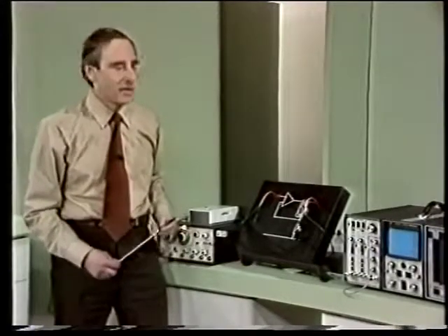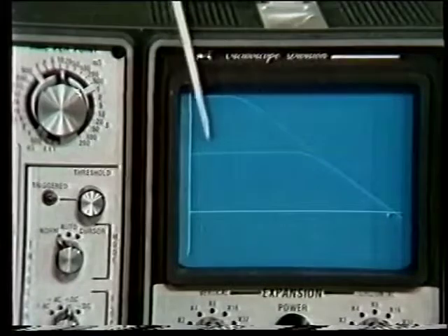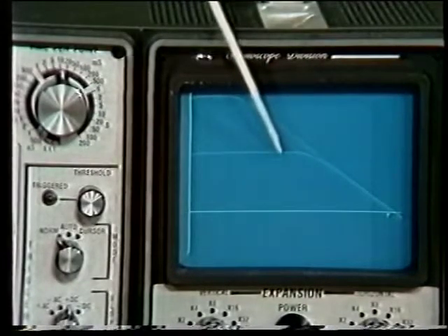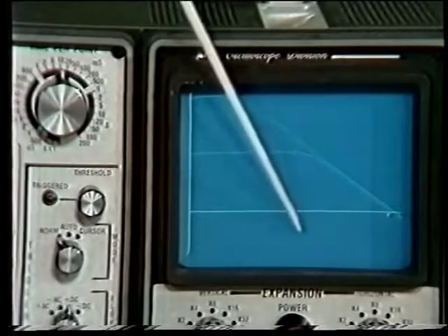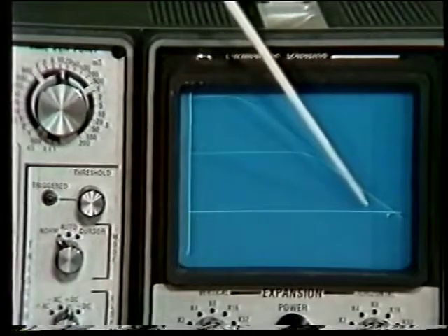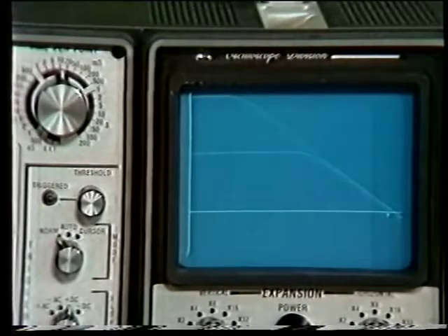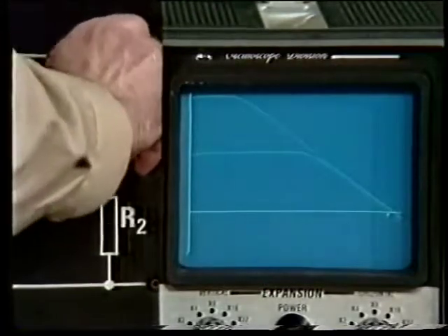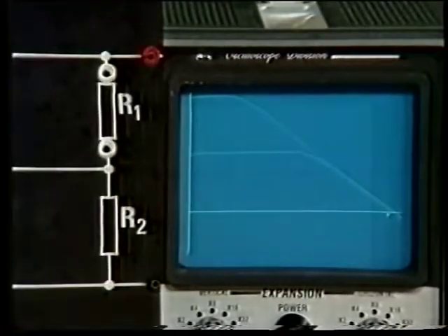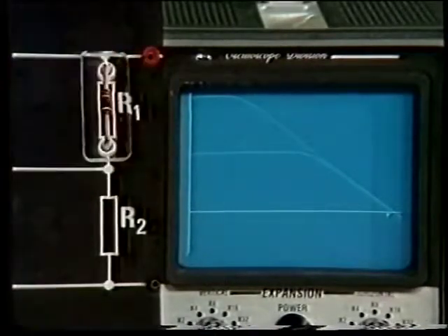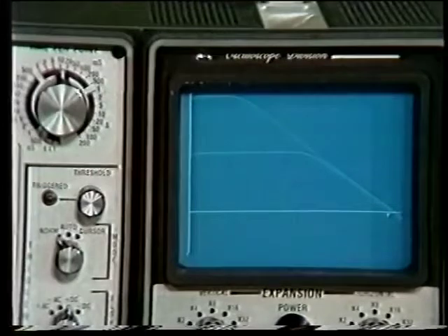Now for the second curve with R1 equal to 99 kilo ohm. The gain for the horizontal bit is 40 dB, that's 100. The 3 dB frequency is at about 10 kilohertz. Then the two curves join together. I'll just plug in a second value of R1. I'll use 9 kilo ohms. And I'll start the sweep.